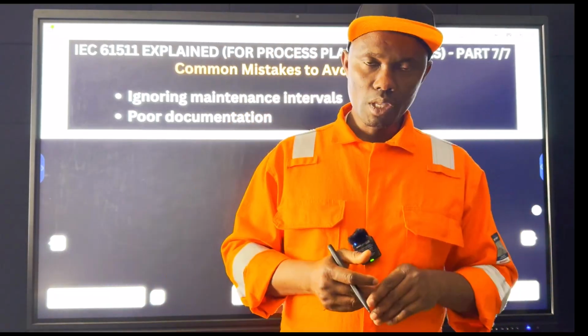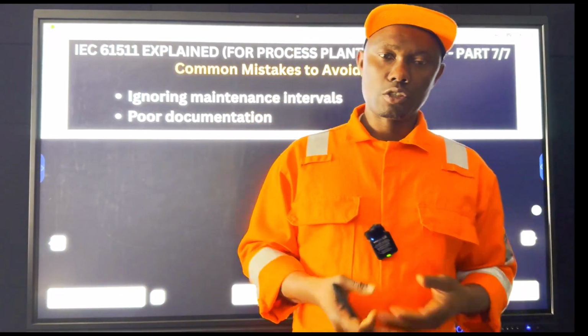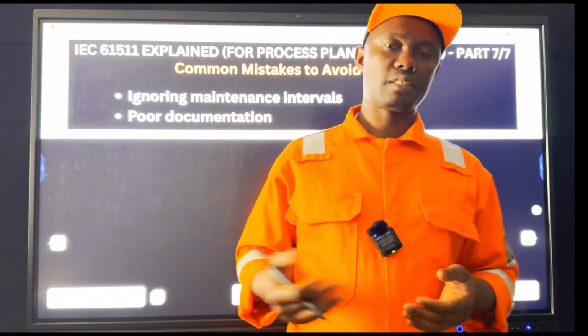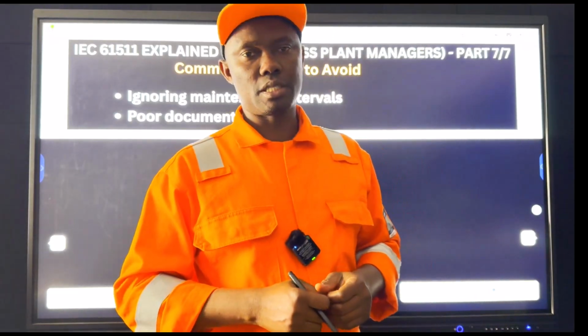If you do any modification on your safe loop, for instance, you really need to go through the MOC process, go through your impact analysis, then develop your modification work pack, go through all the processes and still do your functional safety assessment. Every safety related document and other documents that relate to it should be up to date.